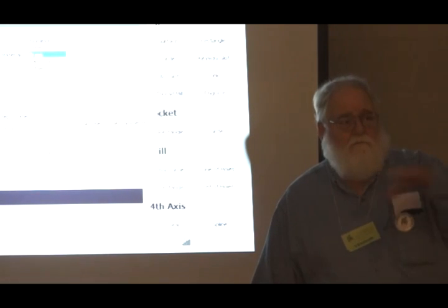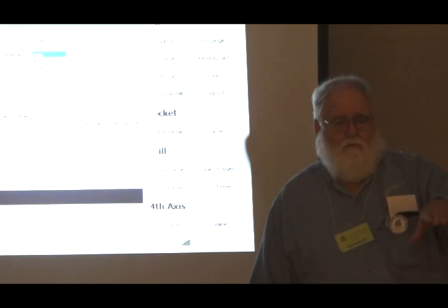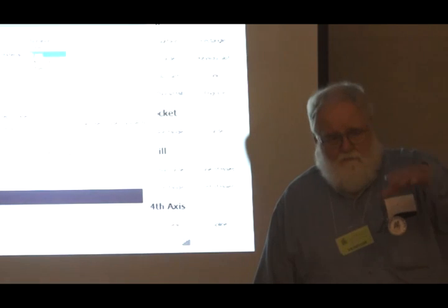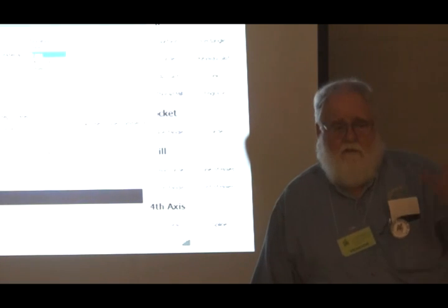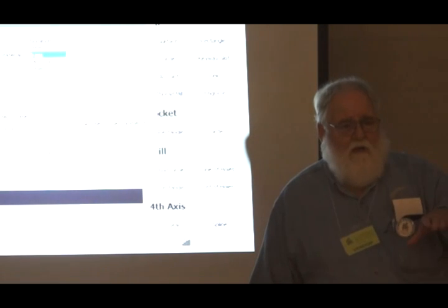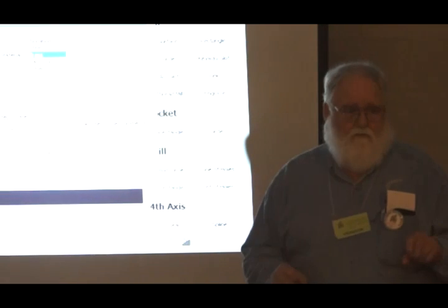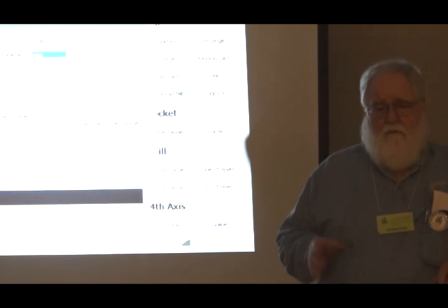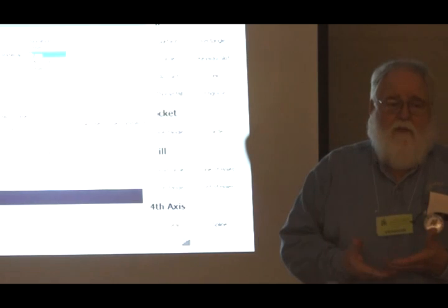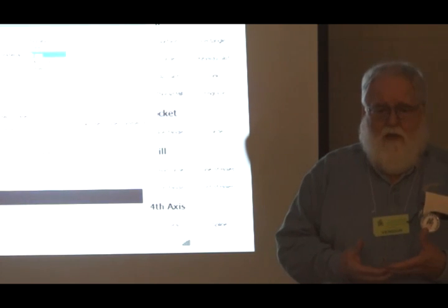I can make the 40 thou steps as you prescribed, and then make the last cut whatever it comes out to be. So I may make a bunch of 40 thou cuts, and then a 2 thou cut for the last cut. One strategy is as entered: you ask for 40, I'm going to make each step 40, but I'm going to make the bottom come out where you tell me the bottom is.